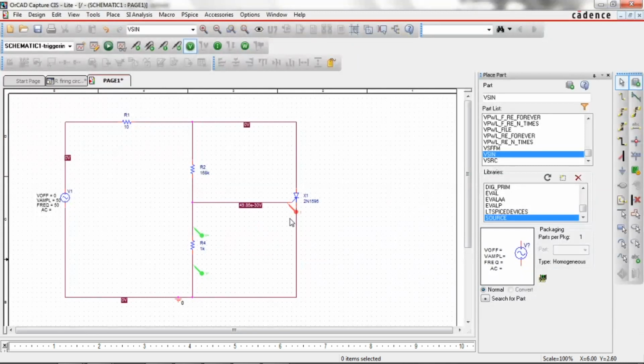So the only requirement is that we need to generate that minimum voltage, 0.75 something, but this is only for this SCR. That much voltage I should generate here, so that I supply a current in and around 2 milliamps, 1.9 to 2 milliamps of current. Then I think you understood the logic here.